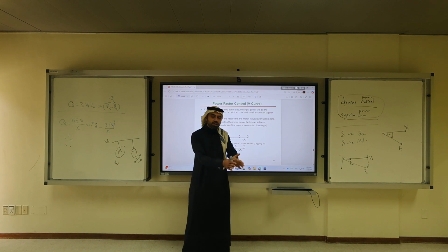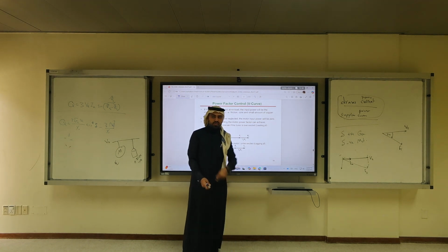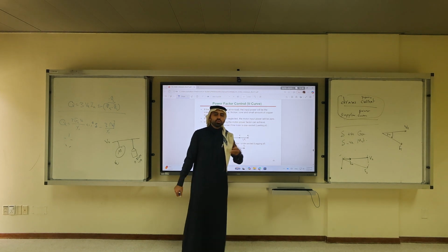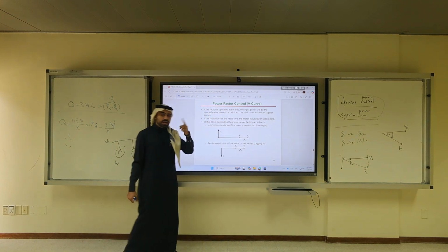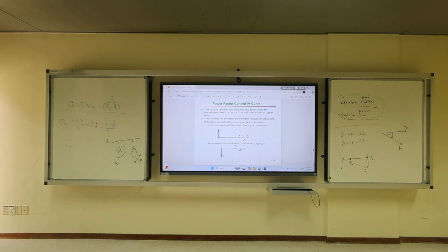I don't have a shaft. The shaft is spinning in the air. My load is the air. If my load is the air, my input power is too low. Can I say it's 0? Yes. So those motors are synchronous condensers. They spin without any mechanical load connected to them.